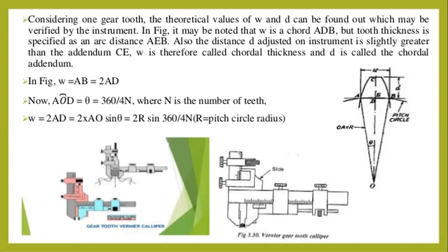And also the distance D can be adjusted on the instrument to be slightly greater than the addendum CE. That is, CE is the addendum.